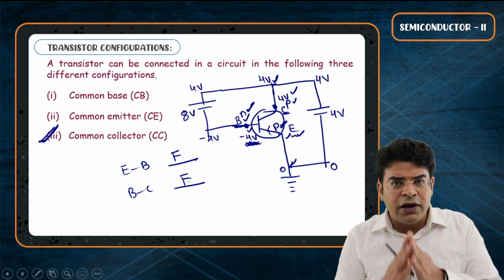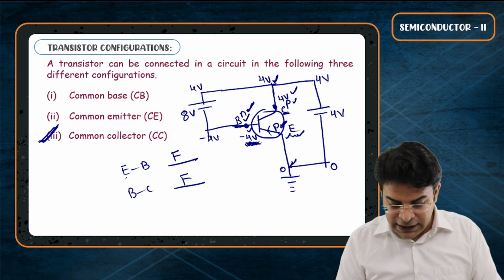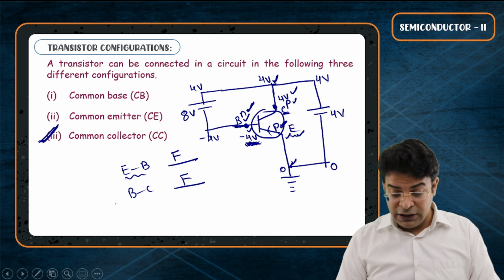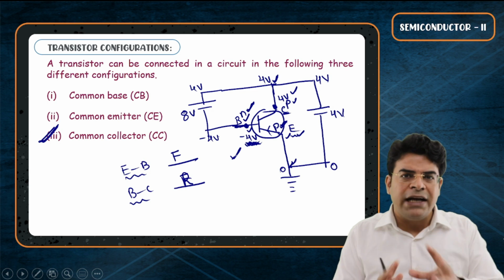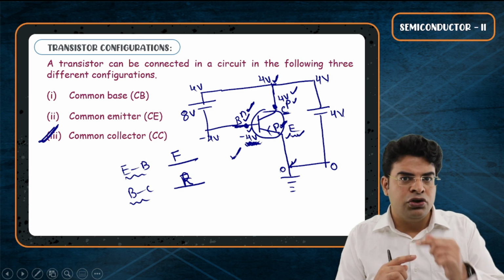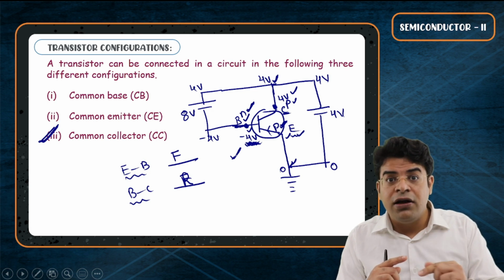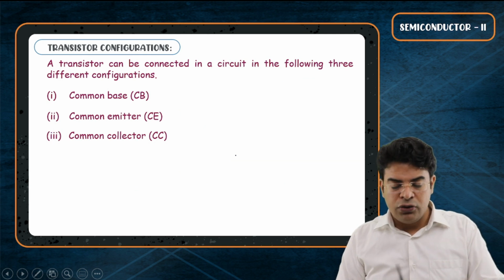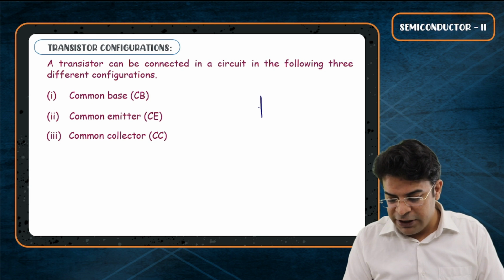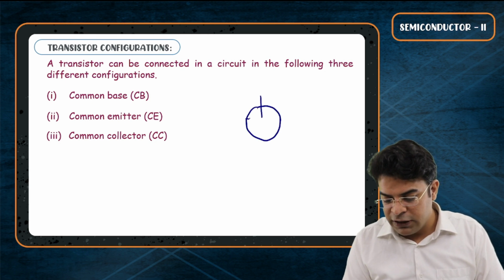For the usual working of a transistor, the base emitter junction is kept forward biased, but the base collector junction has to be kept reverse biased. So that's why this particular figure does not show a transistor under its proper working condition. Let me take one more example to understand. First of all, tell me kids, which type of transistor is this?